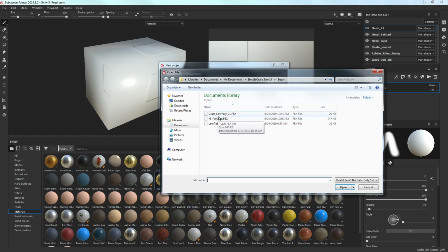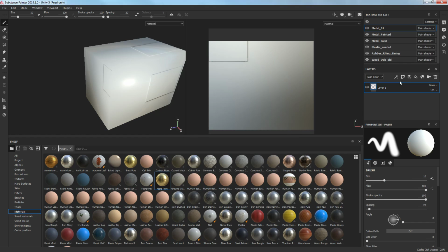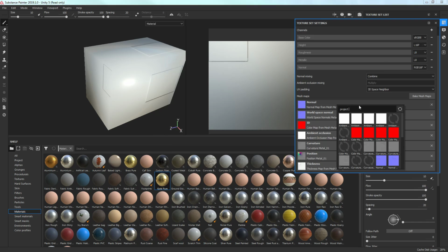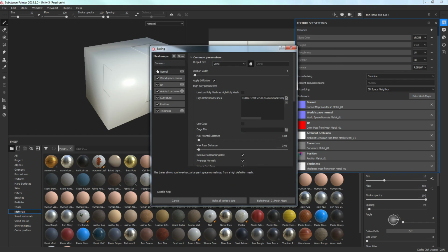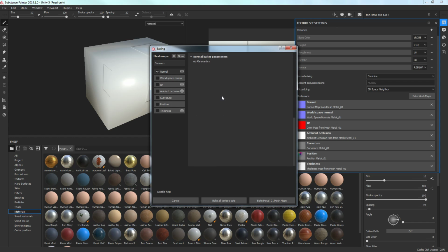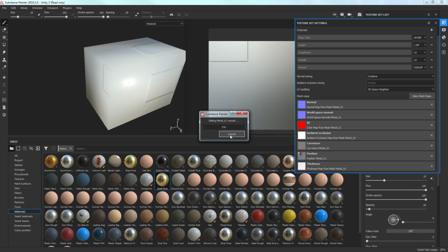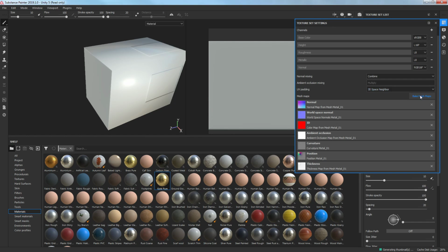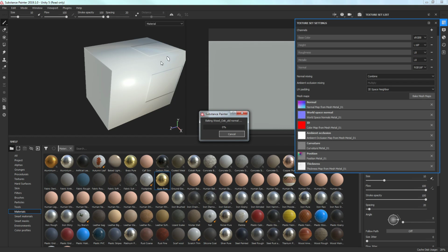Why do you have to reset the project? Because it's using the original normals. Well, let me see. Maybe I just have to rebake it. If I go into normal, I can actually rebake just what I want. So if I bake mesh maps, I can uncheck everything. Go to normal, which is common here. That has the high poly still. So I'm going to bake normal mesh maps. Oopsie, cancel that. Hit the wrong button. Bake mesh maps. I have just a normal on there. I'm going to bake all the textures. And let's see if that actually works. I may not have to re-import it.